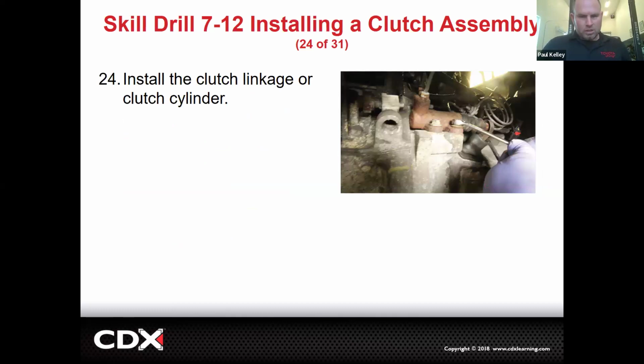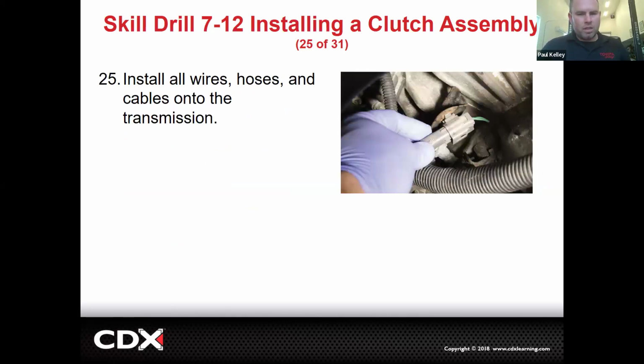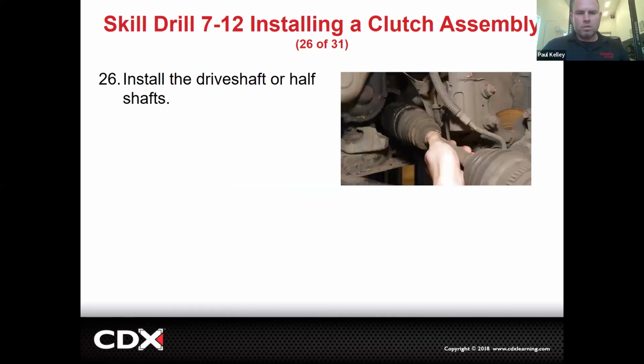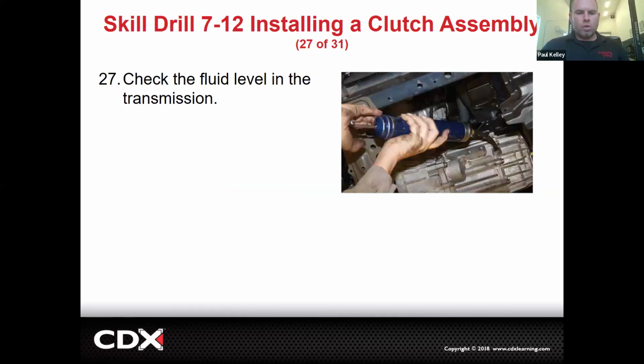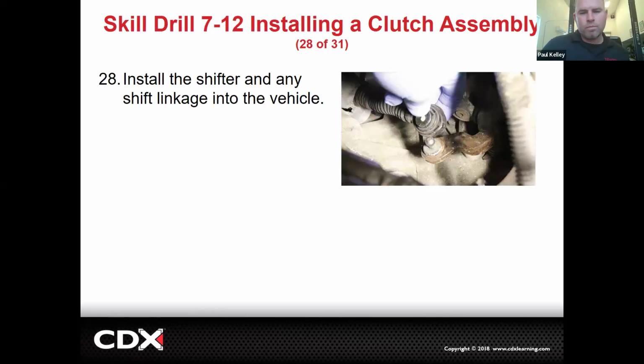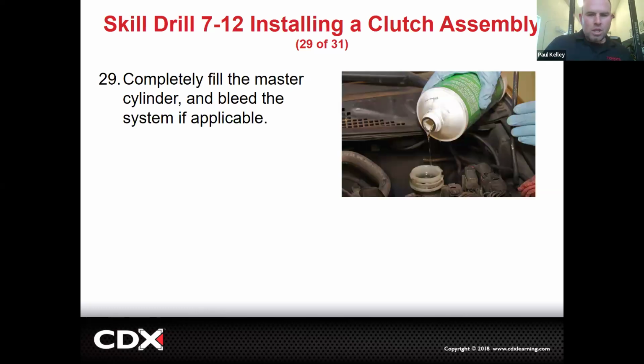And then you guys know we're going to put the slave cylinder on. Hopefully you don't have to bleed that because you never opened it. But if you did, you might have to bleed it. Do cables, half shafts, drive shafts, fill the fluid level if you drained it. If I'm doing a clutch, I'm not even draining the fluid level for the record. But if you did, cool. Sometimes it's got shifter linkage. Sometimes it's got a big shifter. A lot of it's really transmission R&R, by the way. But basically, you button this up.